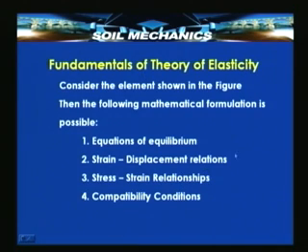With the help of these formulations, we shall be in a position to compute the stresses in the medium. What are the formulations? One is equations of equilibrium. The second one, strain displacement relations. We shall be formulating also stress strain relationships, and then lastly compatibility conditions.